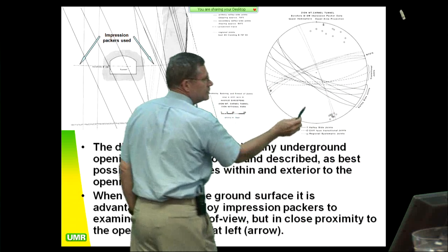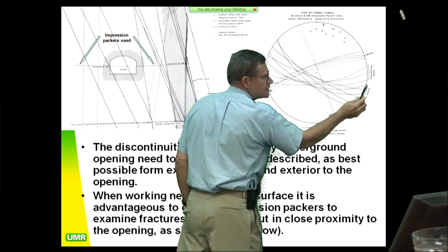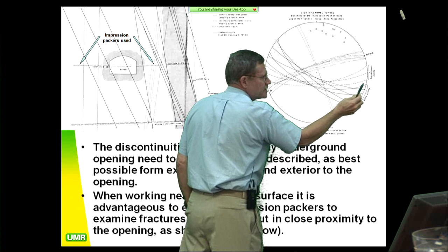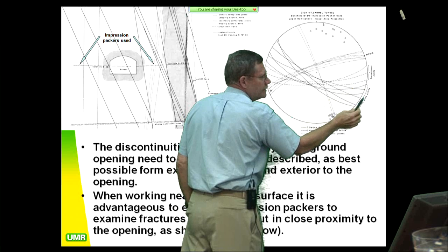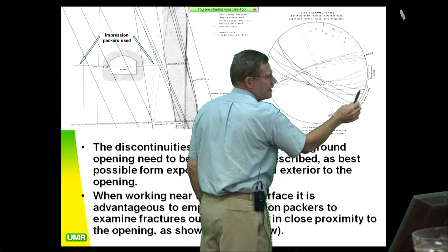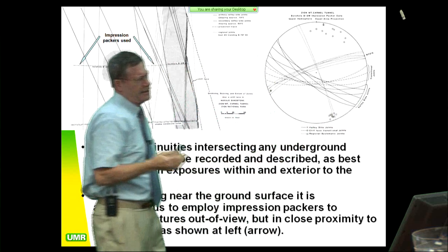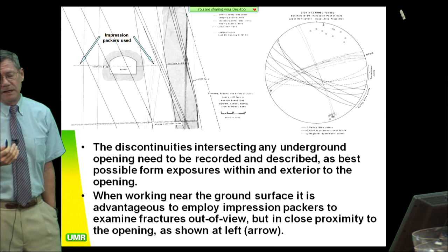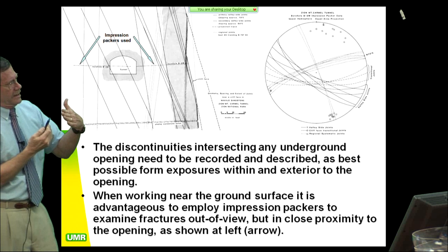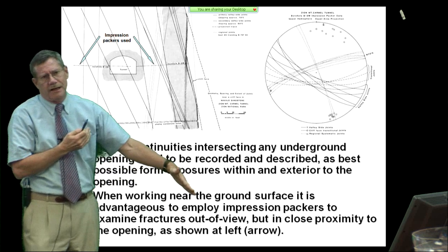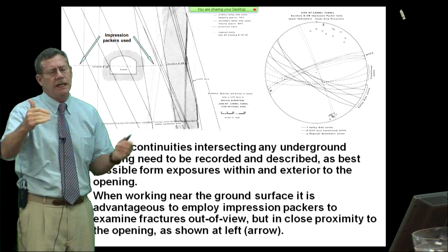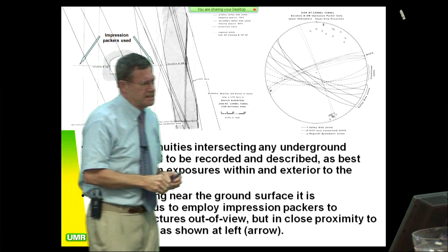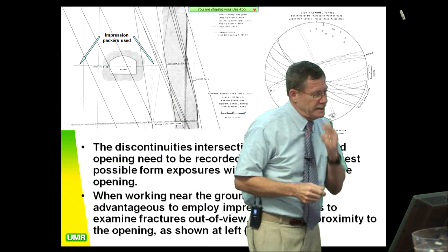These are the valley side joints, this group, and then these are transitional ones. And the transitional ones were the aberration. So you have a big variation, and that's because these are secondary joints. Their genesis is geologically, they're very, very young, they're very recent, and they're forming in reaction to the excavation of that canyon. So they don't have a clean geometry. They have a highly varying geometry. So that's the kind of stuff that really you have to exercise a lot of judgment on.